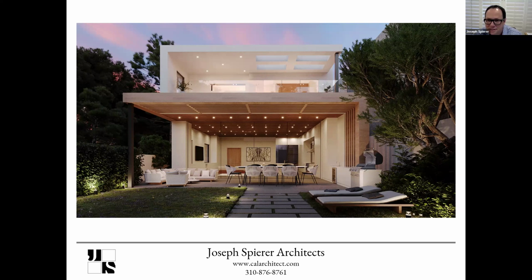Did that answer your question, Jason? Pretty much. I was just wondering if there was a guideline. So we just got back some plans for a home that requires caissons. The distance to bedrock varied from 6 feet to 24 feet. And the rule was that this particular site required about 12 feet embedment into the bedrock, right? So 12 feet plus the depth of the soil up to the house. So sometimes they were 40 feet deep, and other times they were 20 feet deep. Thank you for that question.